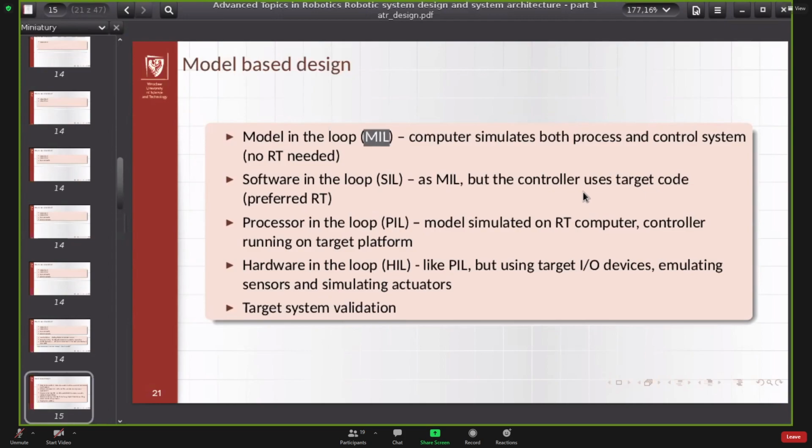It uses the instructions that are available for the microcontroller, and also some specific features, which may be limited compared to your general simulation software. That's why it gets a little bit more realistic. It doesn't need to be real time, but it is preferred that it works in real time too. So the time steps or the clock frequency for the microcontroller is the one that will be on the destination system.